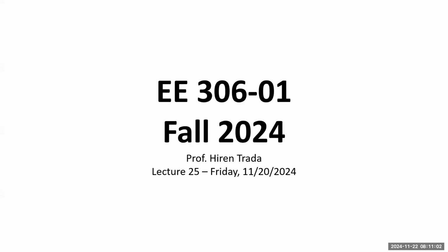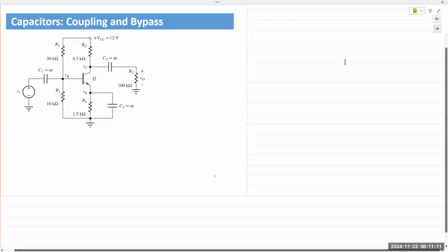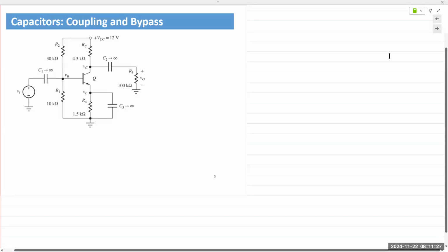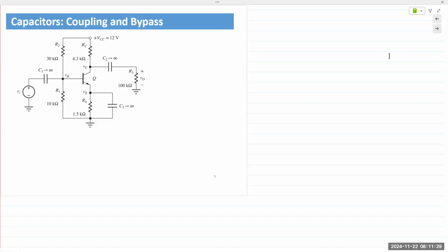Okay, so today we'll cover small signal models for the diodes and the BJTs. Let's see. So we spoke about the common emitter amplifier. The common emitter amplifier, or any kind of amplifier, basically is a combination of AC and DC, right? So we're analyzing both the DC sources that are being applied as well as the AC input signal that needs to be amplified. The way we analyze these circuits is due to the method of superposition.